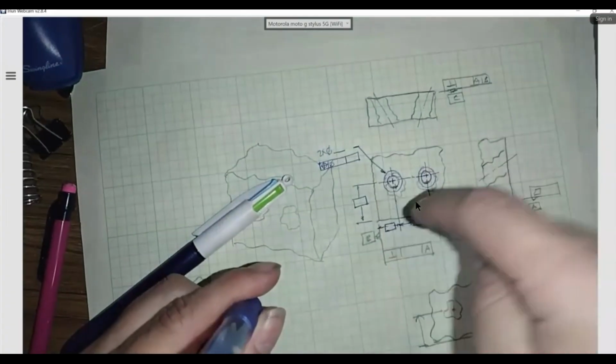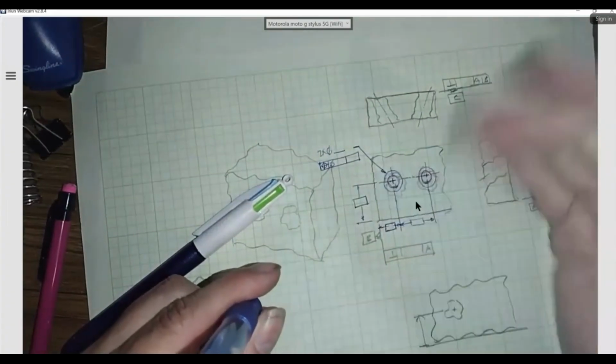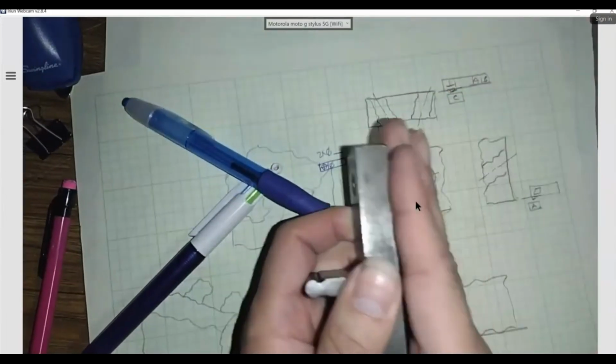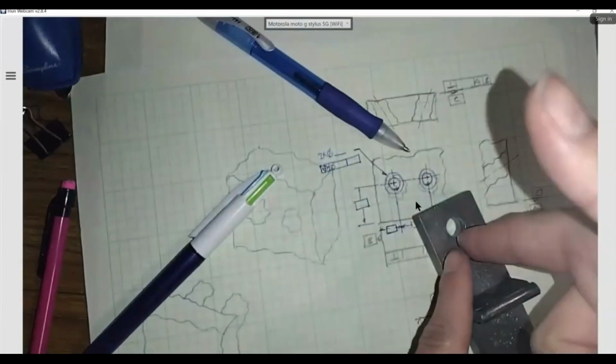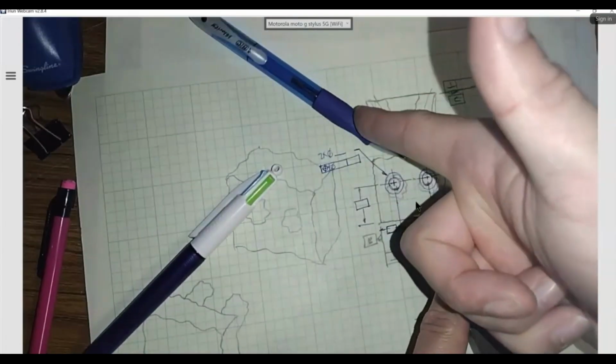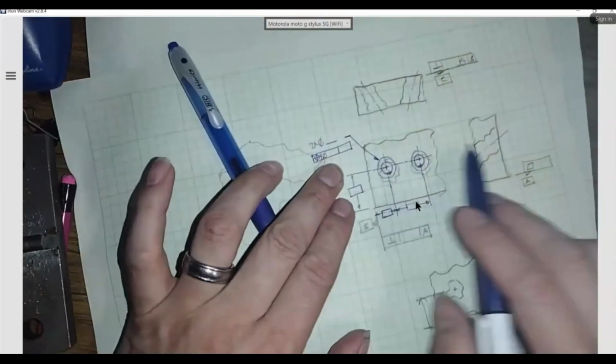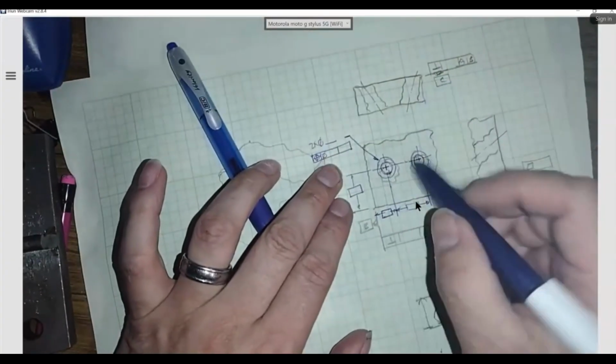Right now, these are holes that I go all the way through, right? And I want them oriented perpendicular to the back. These are the holes. I want to make them perpendicular to this. When you make a hole, you most likely want your drill to go perpendicular, otherwise your hole is going to go sideways. Yes? So you say, I want it perpendicular to datum back, which is datum C.